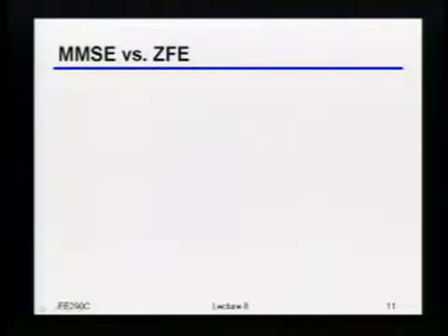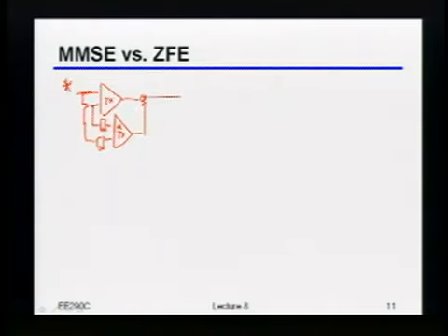The key thing to realize here is that let's say I actually had a transmit FIR. I'll just draw it for the example of one tap here. I implemented my single tap filter over here at the transmitter, and I'll draw it as a differential thing. So this is, let's say, alpha, and somehow I add these things together and send that over into my channel. And now I have my receiver, and I want to figure out how to adapt that transmitter. There's, of course, practical issue number one, which is how you get data from the receiver back to the transmitter to tell it what to do. Let's not worry about that. Let's assume that you can do that.